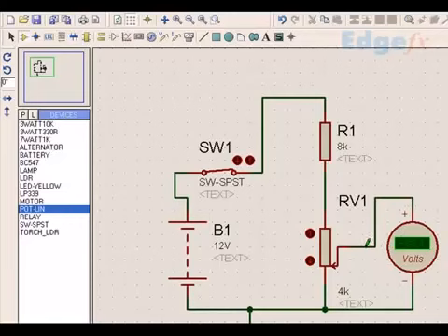different fashion. For example, I delete this, and what I do is, I take this connection and give it here, and give it say here. Now let me see what exactly the situation is here. Now this resistance is 8k, but this 4k resistance is now half of it bypassed. You can see half of it is bypassed. That means the actual resistance of this is about 2k, that is from here to here, because here to here it is bypassed. So it's a 2k resistance.